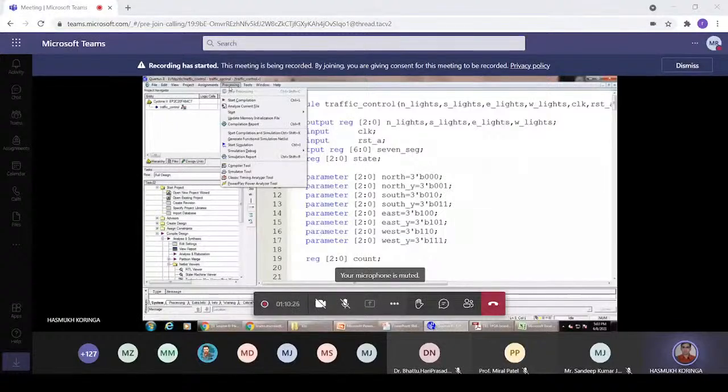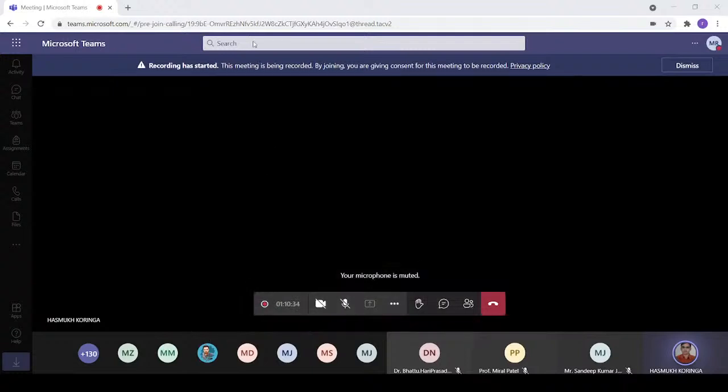So once we start compilation, it does 4 main tasks. One is analysis and synthesis. Analysis, as we know, checks whether the code is as per the VHDL language or not. Synthesis converts the code into the gate level netlist. The second task is fitter, place and route. In place and route, it checks, in the specified selected device, where to fit the logic.